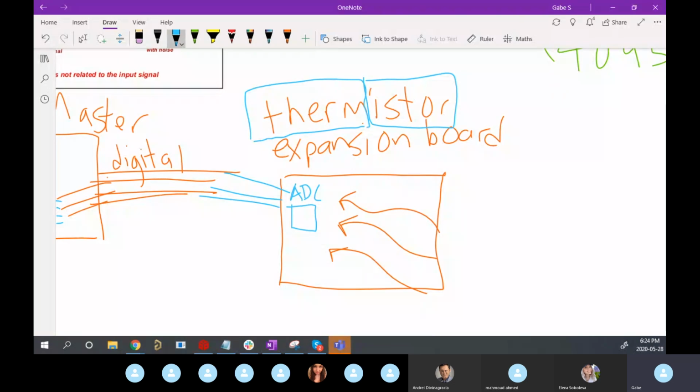So basically, people usually draw them in circuits that look like this. So your resistor, and then you often have a little arrow to indicate that it's variable. So what happens is, as the temperature around the resistor changes, the resistance actually changes as well. And that's really useful because what we can do then is put this changing resistance into a circuit and measure the voltage across it as that changes.